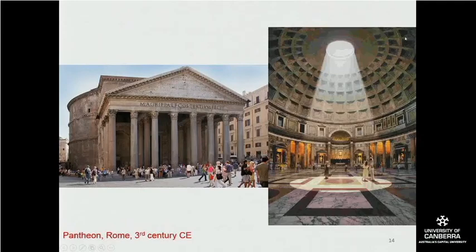This dome with the coffers is actually made of concrete, not reinforced concrete, but just pure concrete. And it's also weak concrete, which is quite amazing, because it's essentially stood up for nearly 2,000 years. These coffers, or cutouts, are really ways to reduce the weight of the entire thing and reduce the use of concrete.